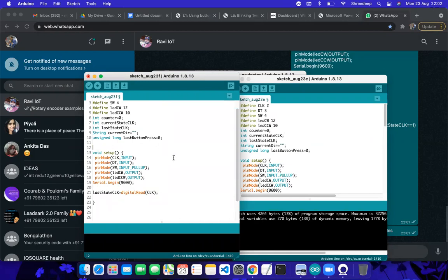Now there are two things to be written over there, apart from all such discussions that we have taken, for example the last one also. See, Arduino pin number 2 and pin number 3 are also called interrupt 0 and interrupt 1. So you can define this, 0 basically means pin number 2.